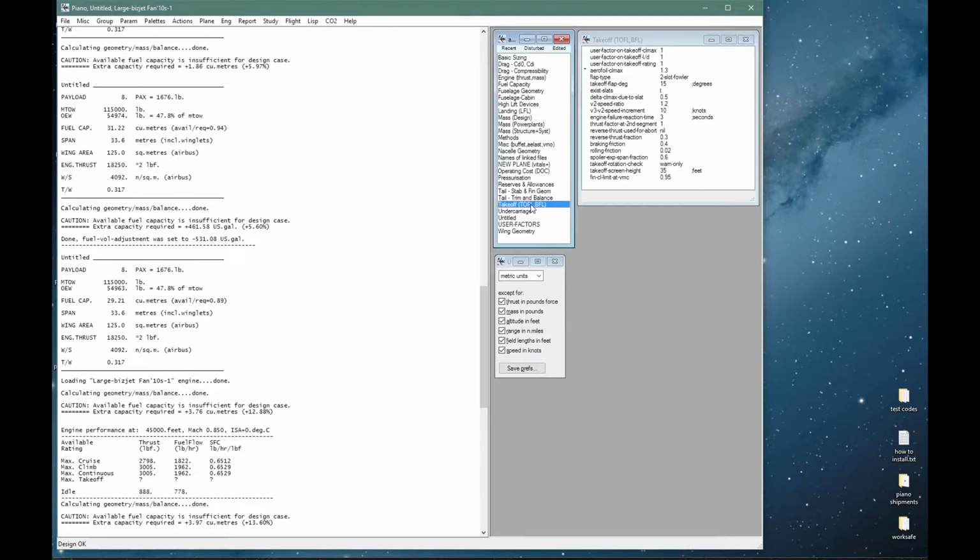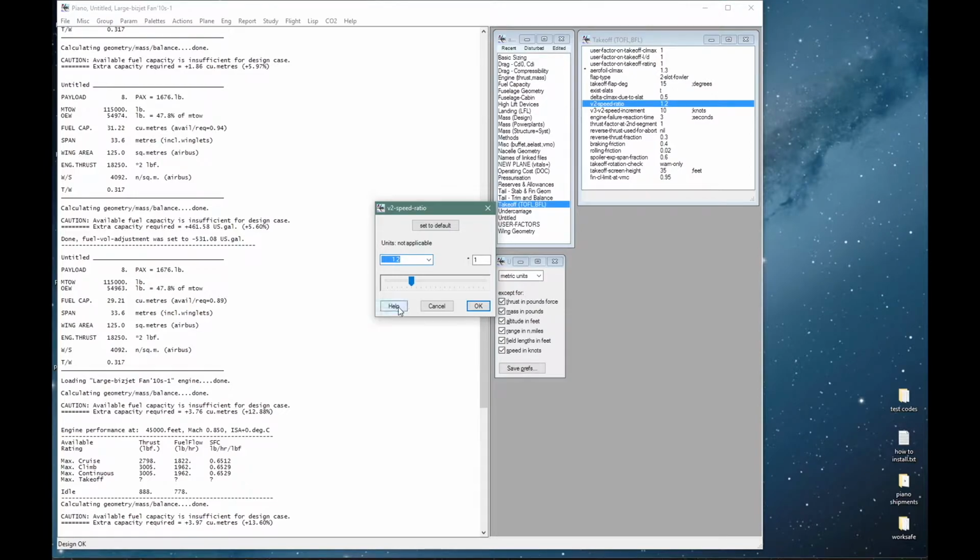Takeoff palette. Business jets have high thrust to weight ratios and can accelerate fast even with one engine out. If V2 is set at its lower bound and the pilot executes an over-aggressive rotation to meet a difficult UFL target, it becomes possible for the wingtips to stall in ground effect. This can lead to loss of control and has happened during flight tests of another type. Now, the presence of slats in the Falcon 10X makes this scenario very unlikely. Even so, I will be conservative and set V2 a little bit higher than I did in previous examples. Instead of 1.13, I will set it halfway between that and 1.2.